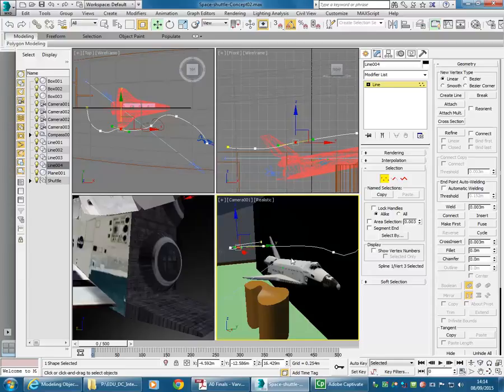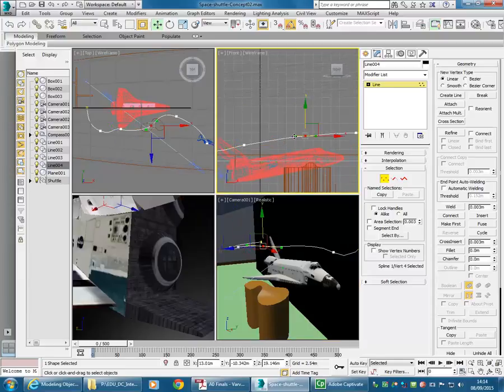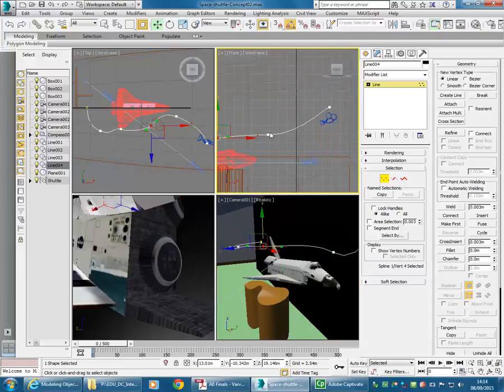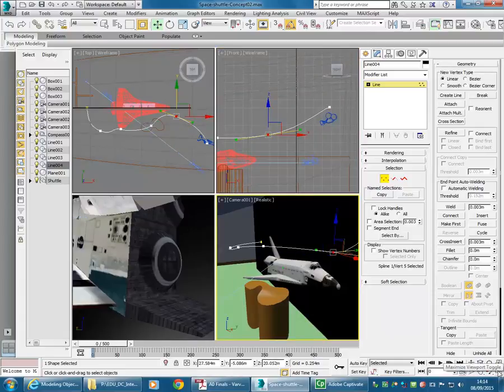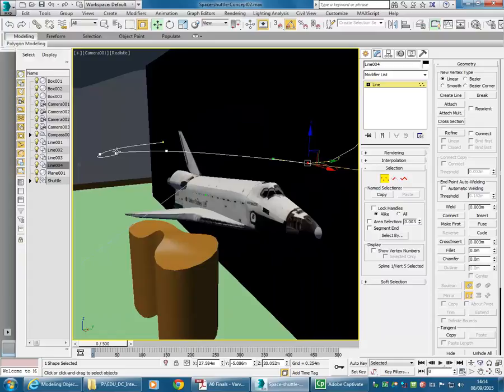So notice in the camera view there, I can see that ribbon type shape that I want. Just so it's clear, I'll maximise that. So there it is, you can see it coming through the view there. And again, unlike Revit, I can keep adjusting that in the camera view. There's no restriction on working in camera views in 3ds Max.